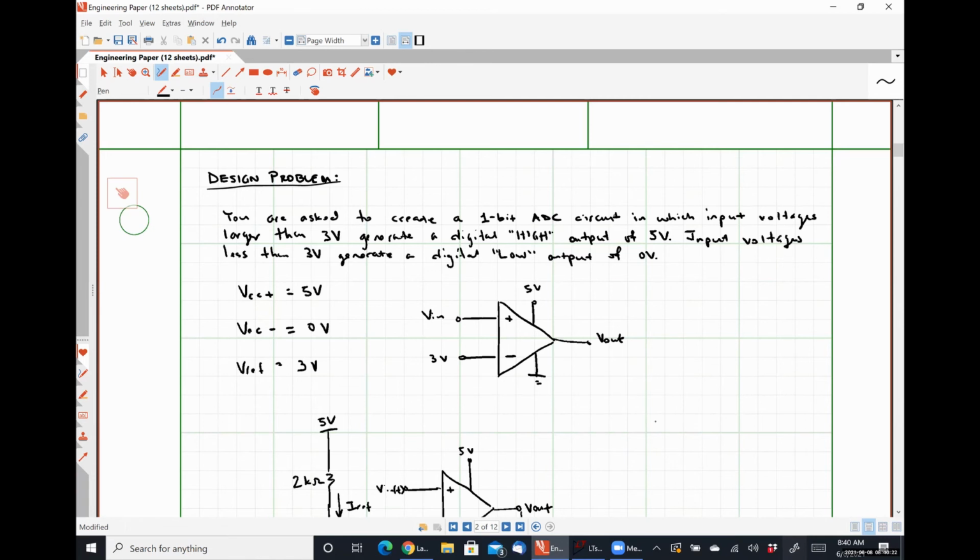Is that a multimeter? So a multimeter, I'm sure there's an op amp in there somewhere, but I guess it really depends on what function of the multimeter you're asking about. So when you're measuring voltages with a multimeter, you're measuring voltages in parallel with your circuit element of interest.